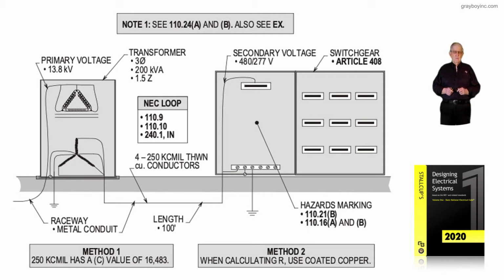110.10 was revised to basically allow the engineer or contractor, whoever had the authority by the state, county, or city, to make this calculation, start at the transformer, figure the available short circuit current there, and size the conductors and the length of the conductors to limit the short circuit current to the point of delivery. And 110.10 just basically states that you could use anything of copper or any kind of resistance in conductors and so forth to limit the available short circuit current.